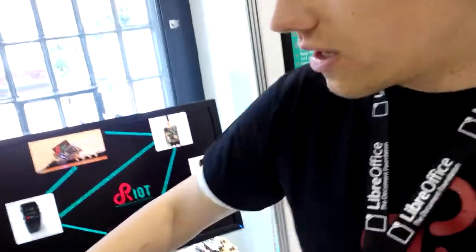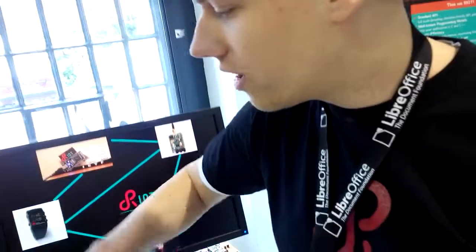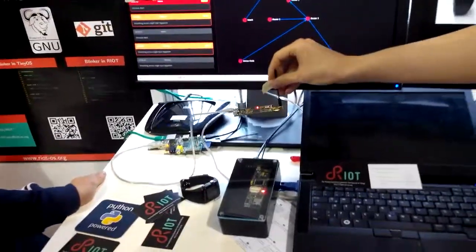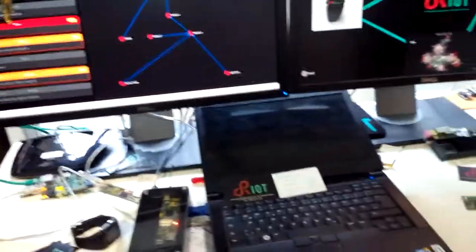So the technology we use is we implemented a subset of IPv6 and the low power adaptation, 6LoWPAN, and as a routing protocol we have RPL running here. All these nodes are just starting up. There's no pre-configured gateway or anything you have to do as the owner. It just starts up and then searches for an RPL network, on demand. And then this portal node here is configured as a root node in the topology, and it sends out these RPL root announcements. All the other nodes are joining in, and it's the way we think the Internet of Things should work.